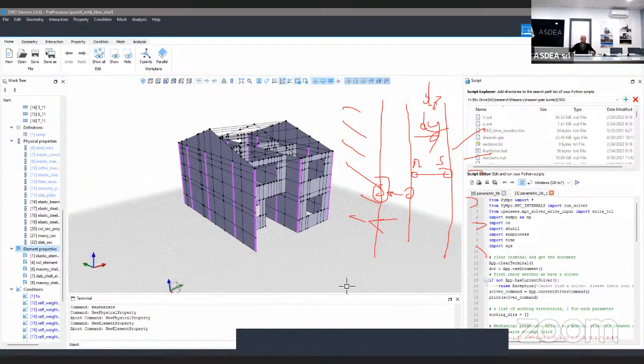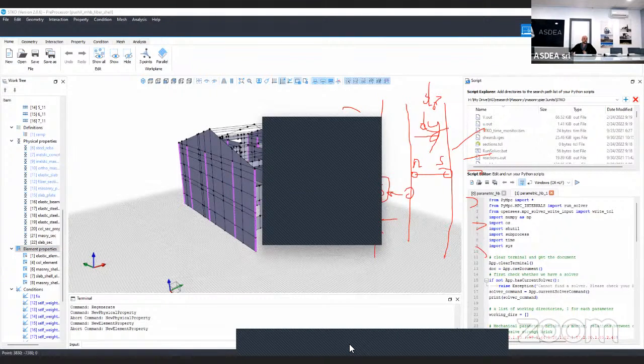Let me go on my computer. I think it was dx, but I need to check it. Just give me a second. So STKO, external solvers, OpenSees, element properties, zero length element is the implex. Then I get the local axis. Where is it? Direction.